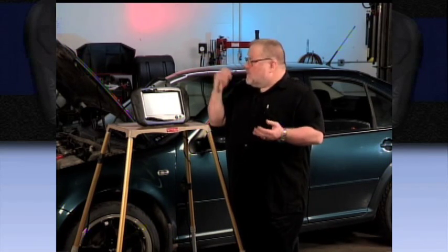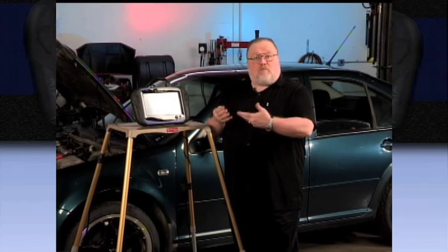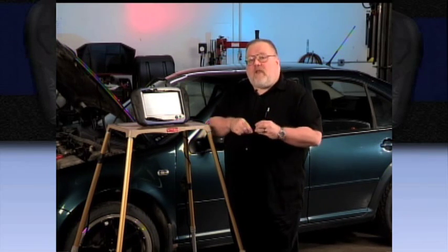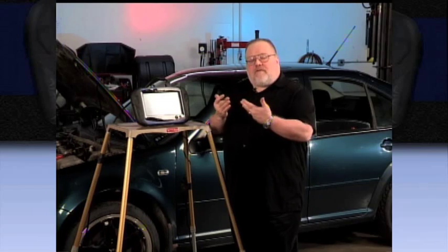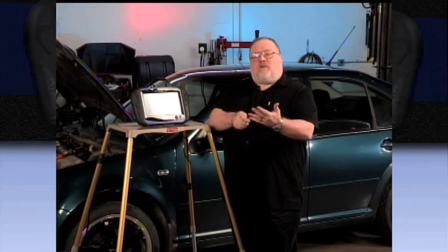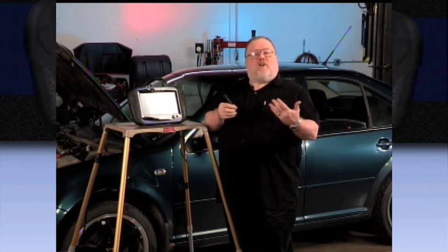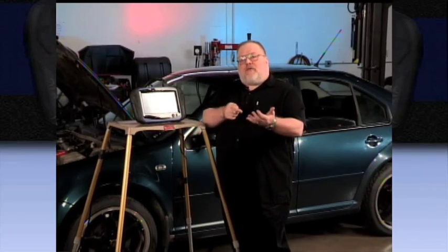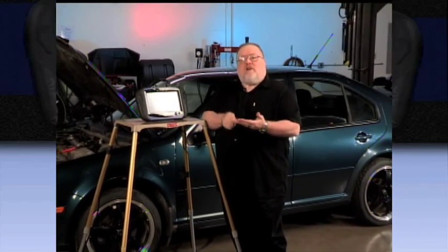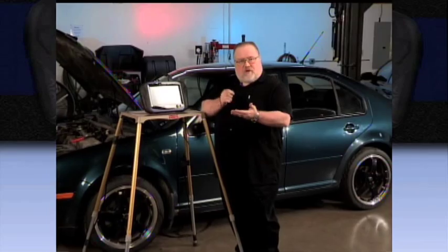Now, in this particular vehicle, this is what's known as a low pressure turbo. It's a 1 atmosphere turbo. So when you're looking at data off the turbo, it's going to show you not only the atmospheric pressure, which is going to be approximately 1,000 millibar, but the boost above atmospheric. So it's always absolute boost or absolute turbo pressure.